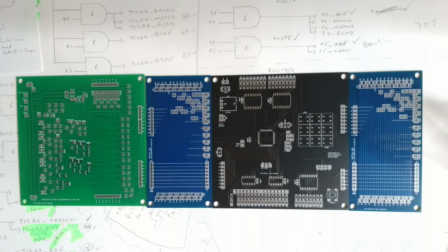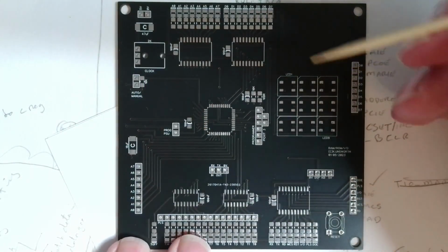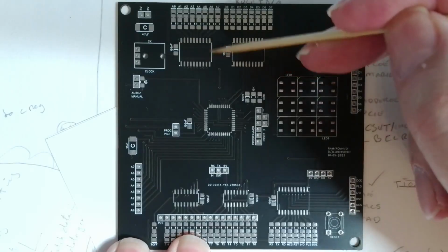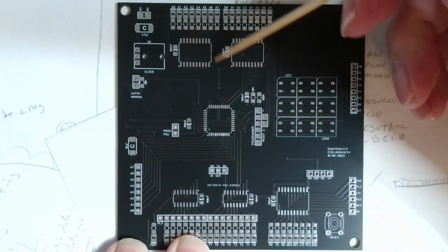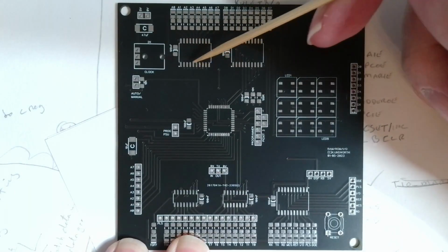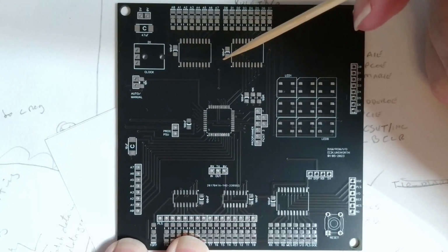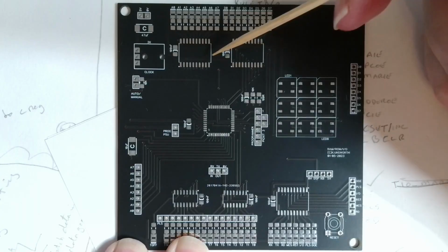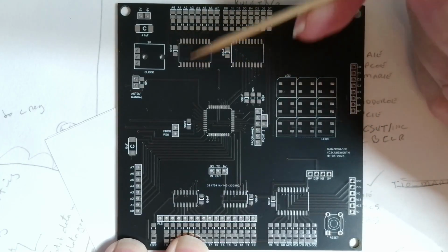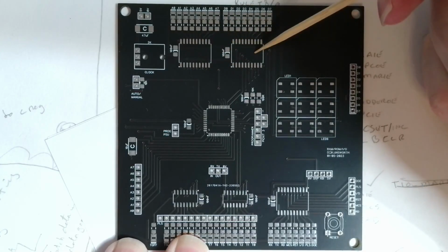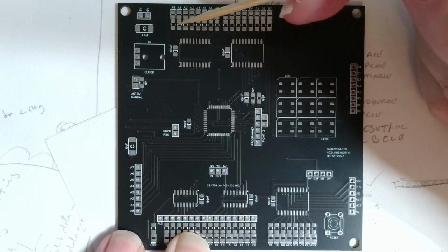Now, if we look a bit closer at the motherboard itself, we've got 2 ICs up here. These are just a row of LEDs for the address and data. I was going to do these with MOSFETs, but it would take up more board space than just doing it with these ICs. So you've got a couple of 74573s. They're normally latches, but they just pass straight through. These are the same ICs as what was used on the logic analyzer. I've got a bunch of them, so I used them here, and they're just used as drivers for the LEDs.